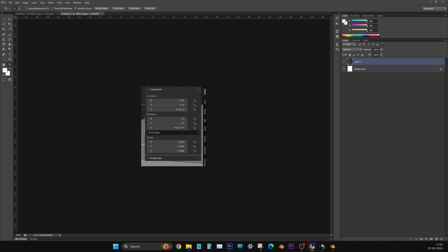Now just zoom in. Yeah, shift. Yeah, very good. Now, if you want the camera to go exactly there, there is a technique. Just press Tab on the keyboard. That is going to edit mode. Select that vertex. Any one vertex you select. Vertex means those points. Now press dot on the keyboard, the numerical keypad dot. Yeah, see, now the camera has gone inside.